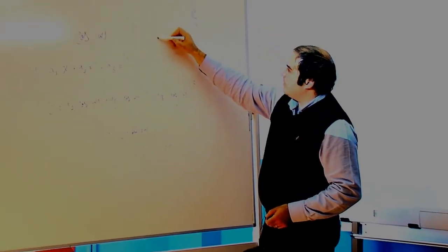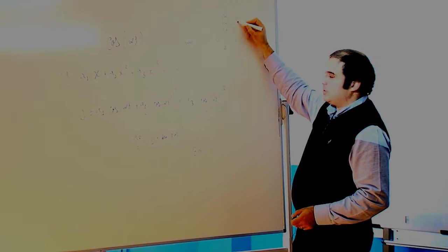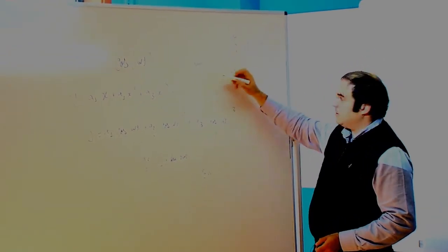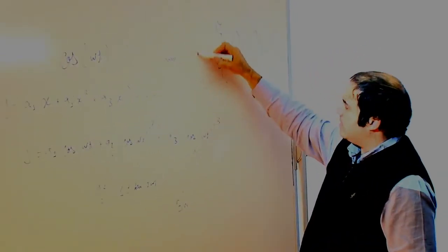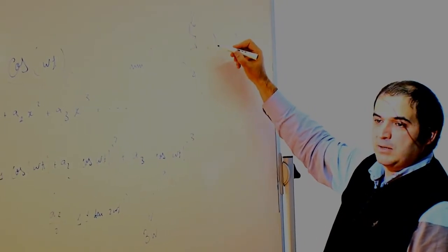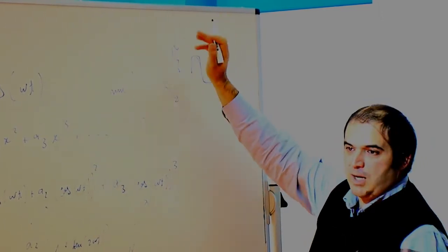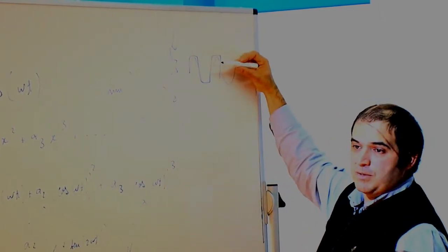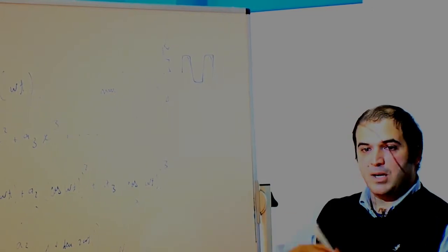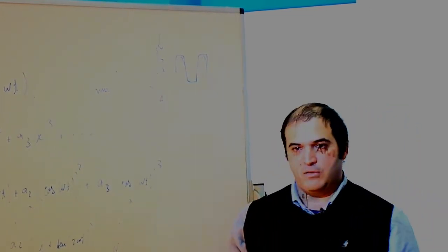What is going to happen? You have a small signal and the output is going to be an amplified version of that small signal. You increase this small input signal, what's going to happen at the output? It starts to collapse, right? So you can increase this as much as you can, but this will not increase more. It will collapse. In the limit, if you don't burn the transistor, you create a square wave.